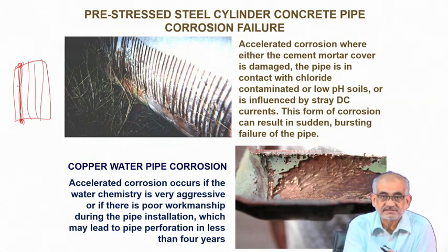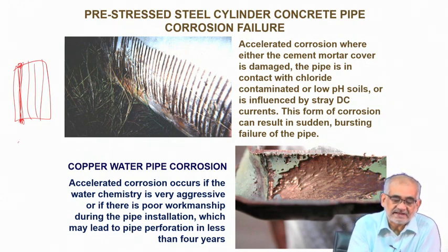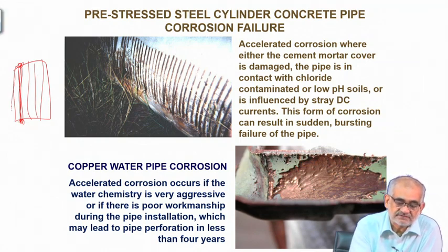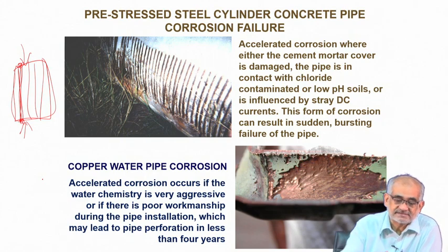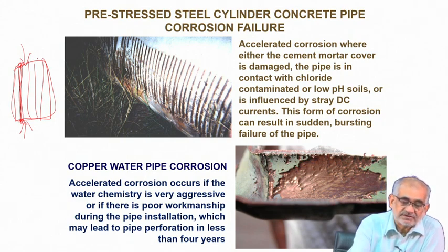And when you cast, then this stress will actually create a residual state of stress on the surface of the concrete, which will be compressive in nature, acting towards each other. So the material, when you release, will tend to relax, will tend to expand, because you applied some mechanical forces to compress them.